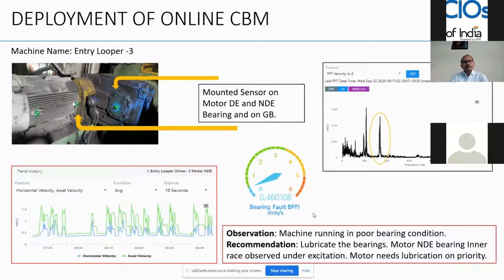It is completely non-invasive. No technique requires it to be invasive. The only place we need to be invasive is for turbines. For turbine applications, these sensors which you're seeing right now on the screen would not work. In turbines, you need something called shaft displacement measurement, which is something that Bentley Nevada does, a company from GE. It is more invasive and more involved.